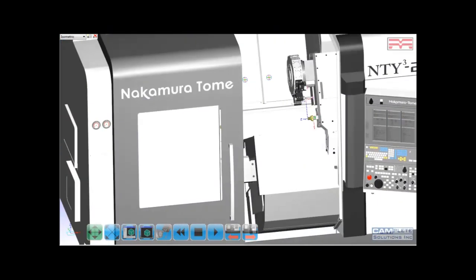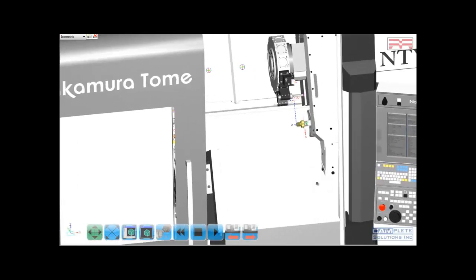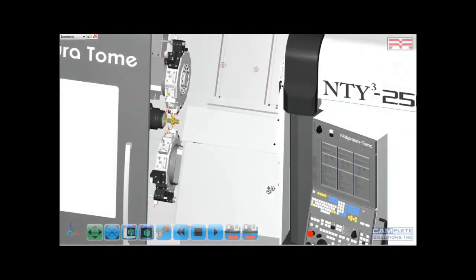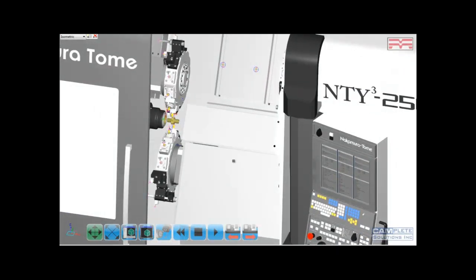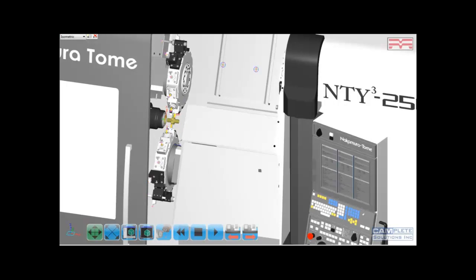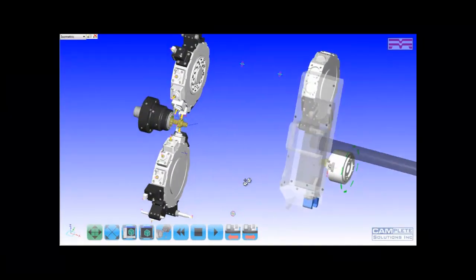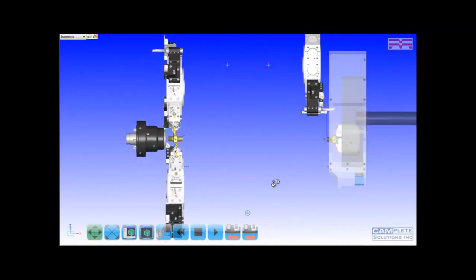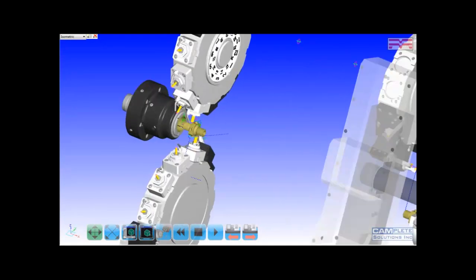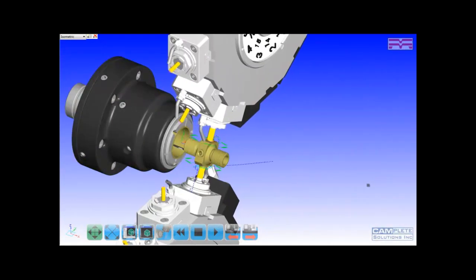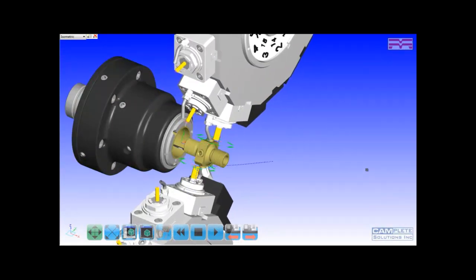This is true verification of the G-code. This is not the same as a CAM system, which verifies a toolpath but never truly, even when the code is posted out in G-code, gives you the true simulation of the part being cut on the machine. This is true simulation, actual time, even accel decel rates of the machine are in this software.